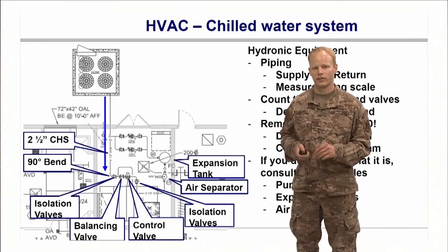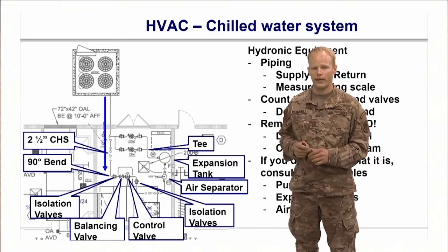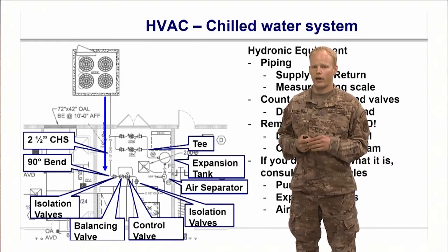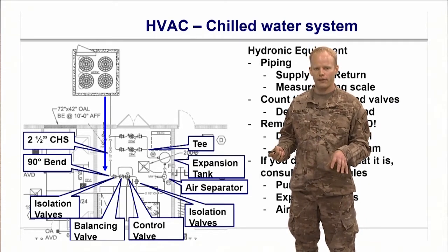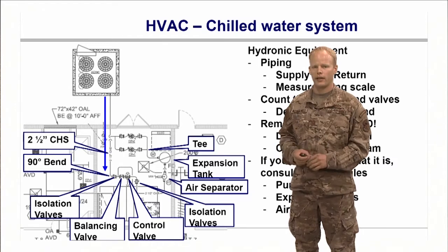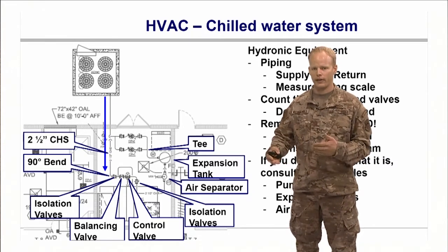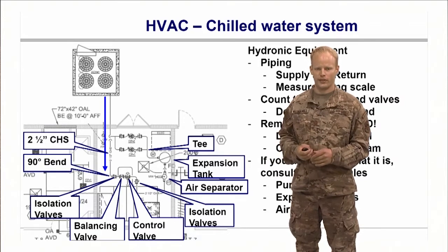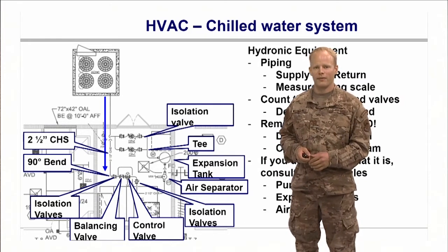We then can come over to a T where we're running 2 pumps in parallel. This allows us to turn one on and turn the other off, possibly remove it, replace it as necessary. Or they could be sized to run together and then you roughly double your flow through the system. Once again, we have isolation valves.